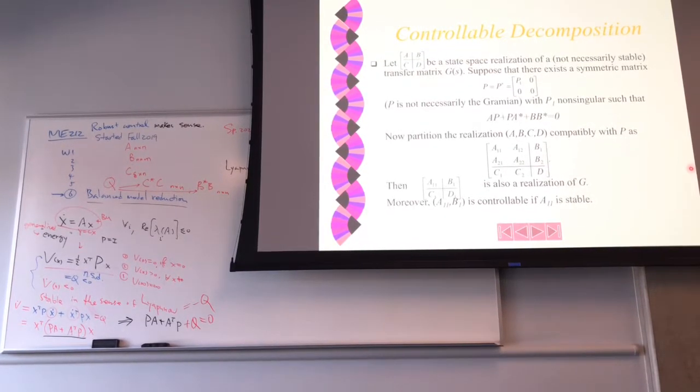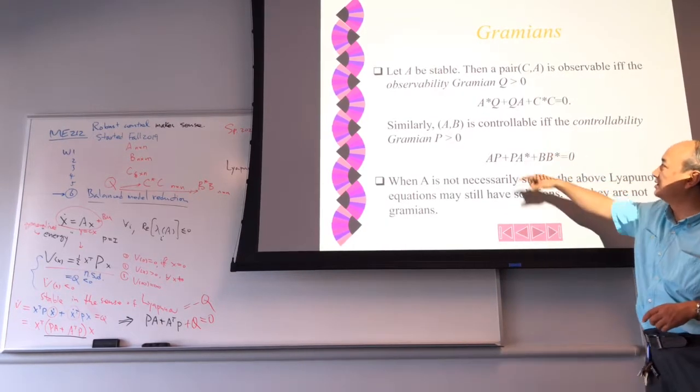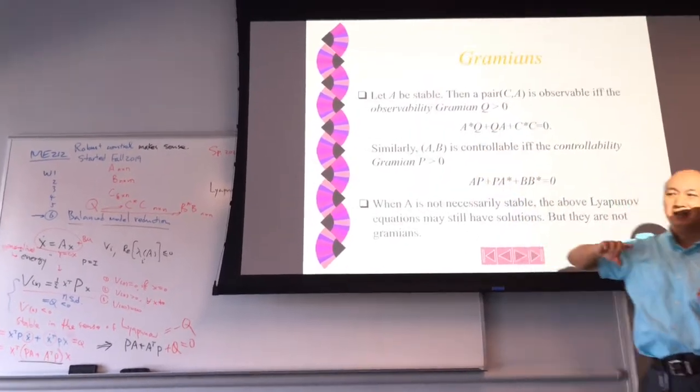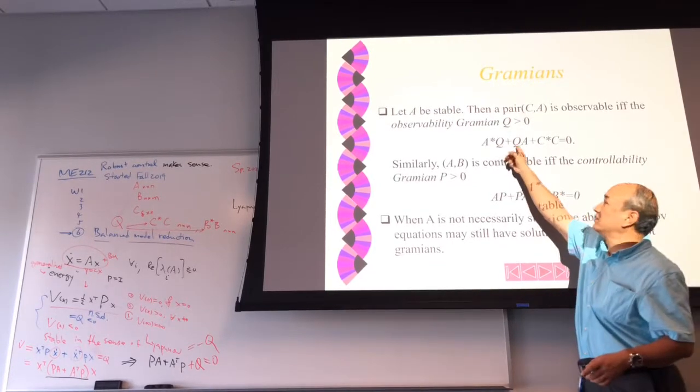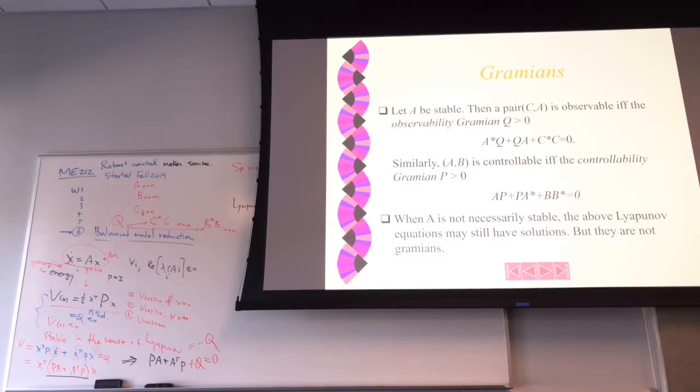If you have A, B, C, then you can talk about using the Lyapunov equation by choosing a special Q, so you have P. I don't like this Q here. You should not use Q here, so I use my Q in my sense. So this is also P. In this textbook, they use P to denote the controllability Gramian and Q as the observability Gramian.